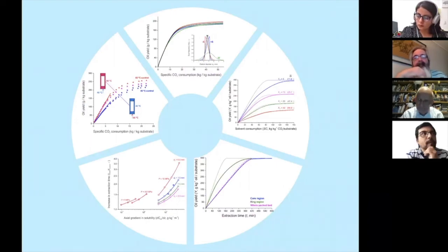Yep, the porosity, the initial concentration of the solute, the inner porosity, and then you define the extraction conditions and the saturation. So basically the solubility of the solute in the CO2 at the conditions of the extraction. Yeah. And then you can simulate whatever size of equipment you want to use, and you can see the differences between the different sizes of the equipment, right?